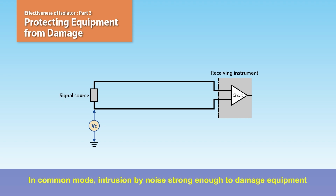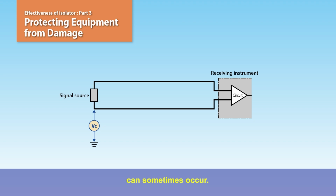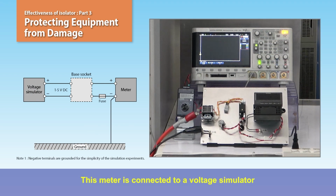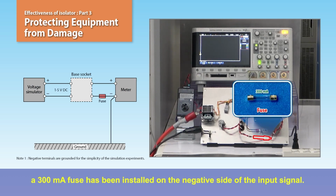In common mode, intrusion by noise strong enough to damage equipment can sometimes occur. As an example, let's examine what effects an isolator has when lightning surge voltage intrudes in common mode. This meter is connected to a voltage simulator that serves as a 1 to 5 volt DC signal source. To confirm the flow of surge current, a 300 milliampere fuse has been installed on the negative side of the input signal.